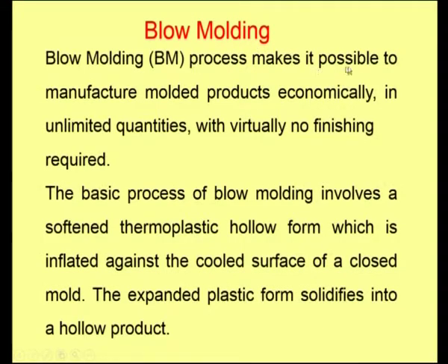Now, the blow molding process makes it possible to produce these molded products in an economical way. That is the principal reason why we go for blow molding, and also in unlimited quantities. One can prepare hundreds and thousands of bottles in one hour or so, and no finishing is required. Post finishing operations are almost nil with respect to the blow molding process.